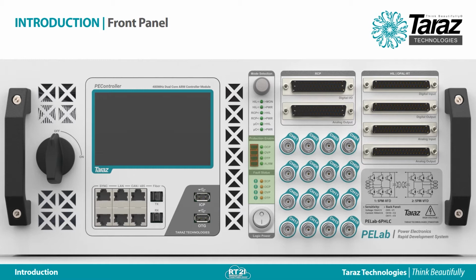We also kept the option for disabling most of the protections. This is required for some loads and topologies. For example, if you are working with the motor drive, shutting down the inverter suddenly can cause an overvoltage condition on the DC link due to the back EMF. In this case, you want the controller to systematically shut down the inverter with a ramp down instead of the hard shutdown that is provided by the protection logic.